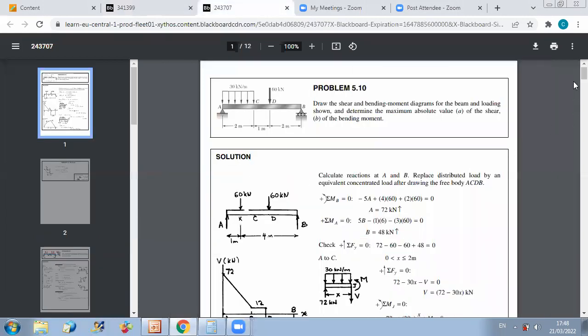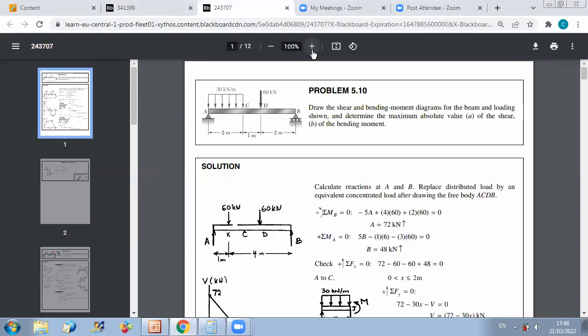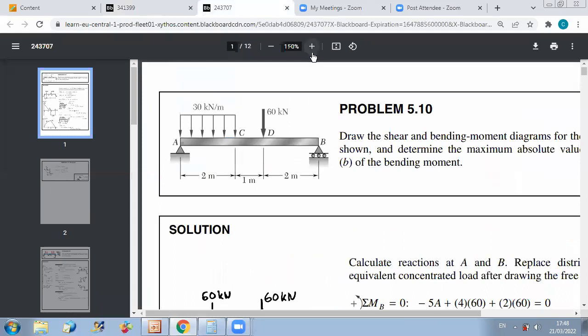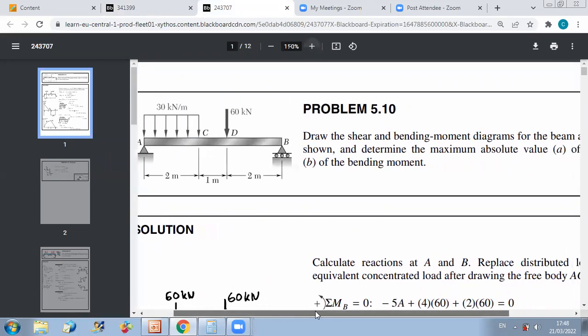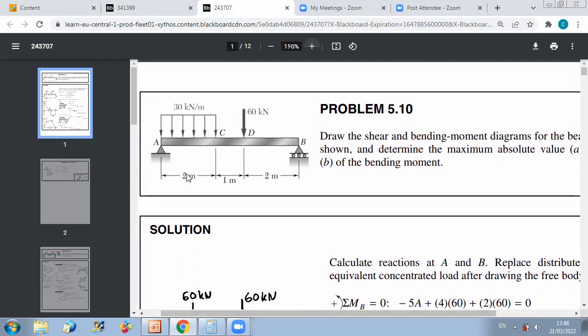Okay, so this is the first problem. In this problem, you have a beam given for you, and this beam is subjected to transverse load. So to remind you, transverse load is a load perpendicular to the beam. We want to first see the variation of shear and bending moment to determine the critical section. As we discussed, since it's a uniform beam, we don't have variation of the modulus S. So to determine the critical section and bending, we just have to determine the location of the maximum bending moment. This will give us a condition on the maximum normal stress in our beam.